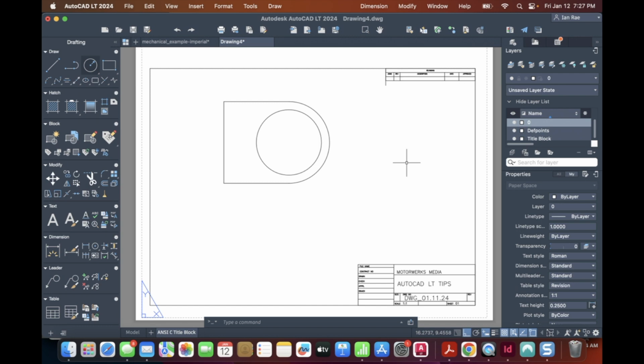So that's a fairly short introductory way of creating circles and lines. Now, to give you just a little bit more, we're going to look at being able to focus on what we're drawing. So we'll use the zoom command, and there are quite a few different ways of doing it. Zoom Z is the one to choose.